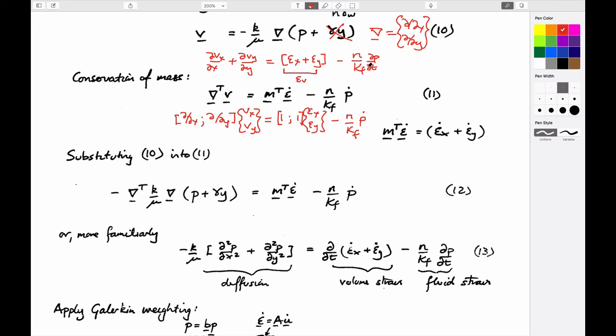And so you get two sources of volume change. You get one because the sponge is compacting and the solid grains are rearranging themselves, so there's less internal volume. There's still the same amount of solid in there, essentially, but because the grains are now more efficiently arranged, you've changed the volume of the system. And if you want to keep the same amount of fluid in there, then you have to allow some to come out. And that occurs with no change in fluid pressure.